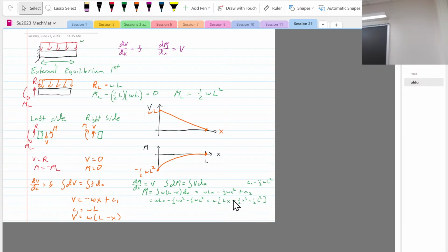Before we even get to drawing the Mohr circle, we have to figure out very methodically which stresses we have, or how they are relevant to the bending moments or the shear force. Or it's a twisting problem, so what's the torque? Or it's an axial loading problem, so it's normal force. Or it's a pressure vessel, so you get stresses in two directions because of the internal pressure.